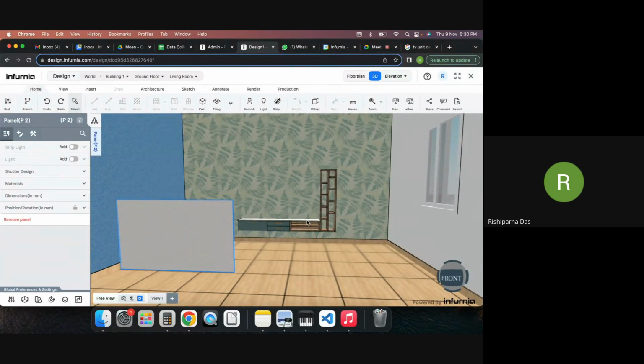You can see that the panel above we had given a 500 elevation, and the panel that I had selected, you can see here that it has a thickness of 12. It's a 12 thickness core material plus 1 laminate. So we can go ahead and create a position rotation, give it a y-axis dimension of 520, let's say.